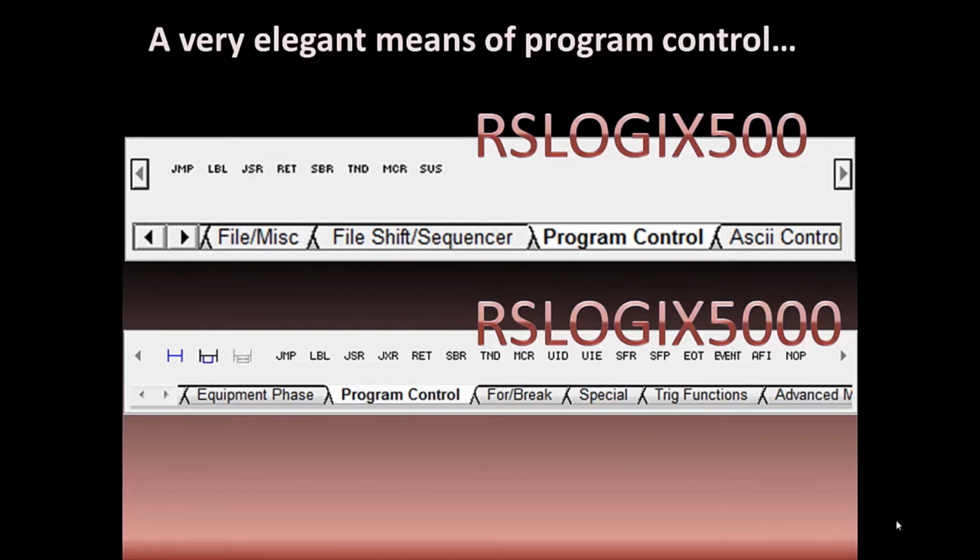And then of course, there's a no operation. That is typically used when an HMI is not available. People will create rungs of logic that are true if on instructions, XICs, with specific tags being addressed by those. And then at the end of the rung, you have a no-op.